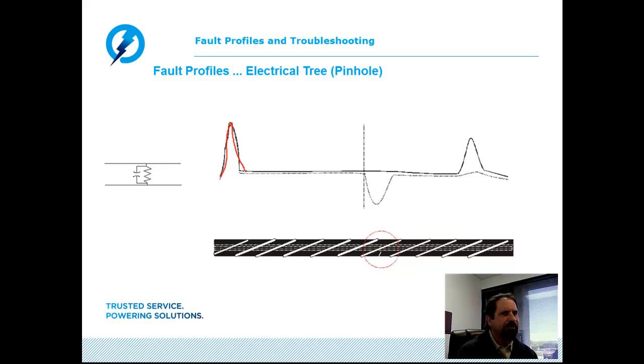the energy leaving the time domain reflectometer, and would more than likely just pass straight past the electrical tree or the fault. Again, the low voltage of the pulse echo device probably would not be able to detect or sense this impedance change, and what we would actually see is just a reflection off the farthest end of the cable where it is terminated in an open.